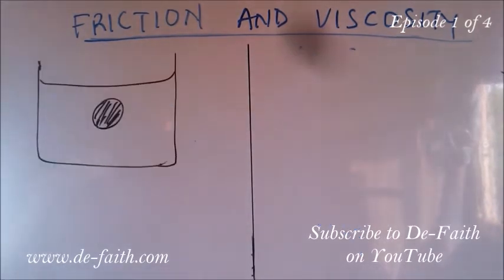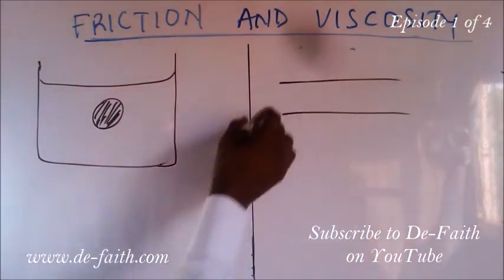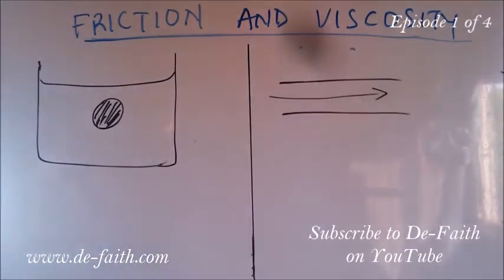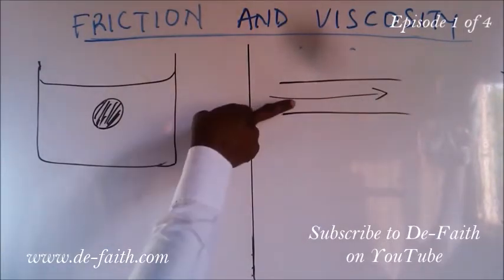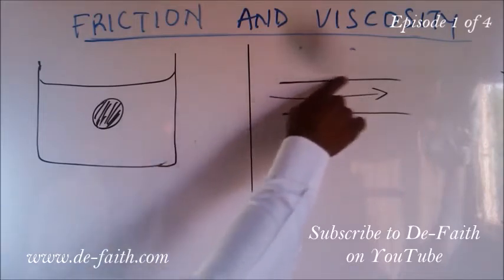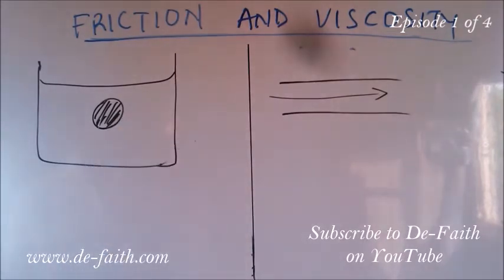Now once we look at viscosity, viscosity is a name that is given to the internal friction which exists between layers of a liquid or gas in motion. If we have a pipe, and in the pipe water as a liquid flows, we would realize that there is going to be friction between the surface of this pipe that's around it and the molecules of the water that's moving.